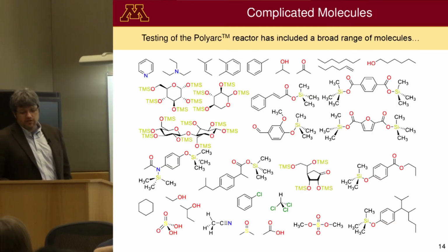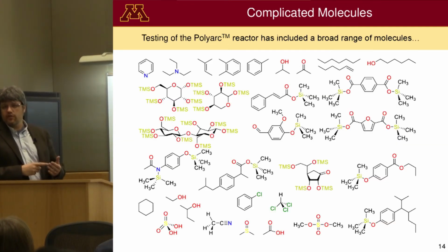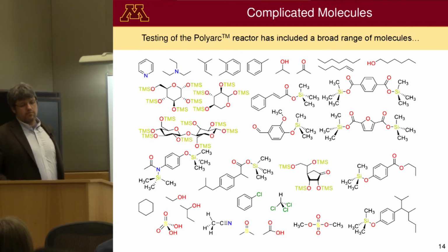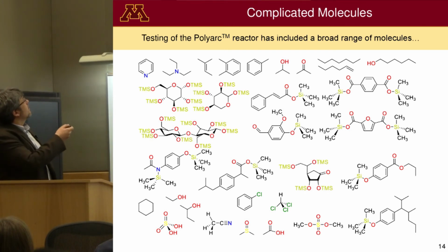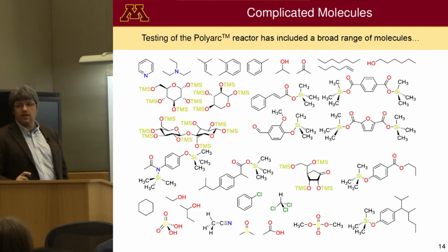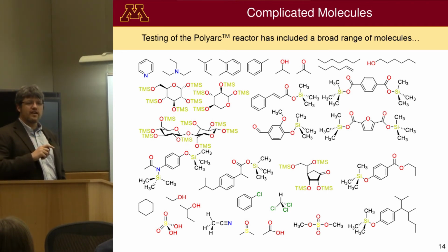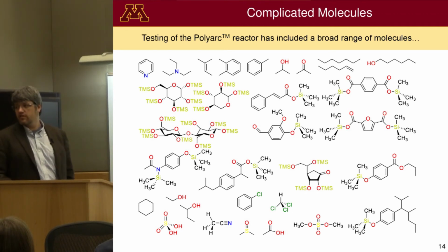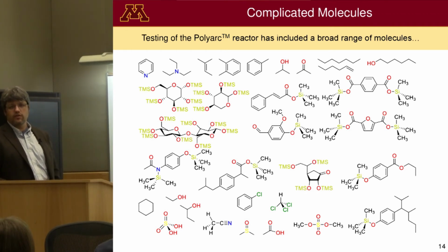What can we use this with? Obviously carbon, oxygen, hydrogen work very well, but we'd like to go to even bigger heteroatoms. So things that are interesting are obviously nitrogen and sulfur. The benefit here is that those heteroatoms don't interact with the FID. If they go through, they'll be oxidized, then reduced to species that won't interact with the FID, and they'll pass right through. And you can quantify the carbon without worrying about the heteroatoms, which for fuel mixtures is critical because there's so much sulfur and thiophenes and things like that in your fuel mixture.